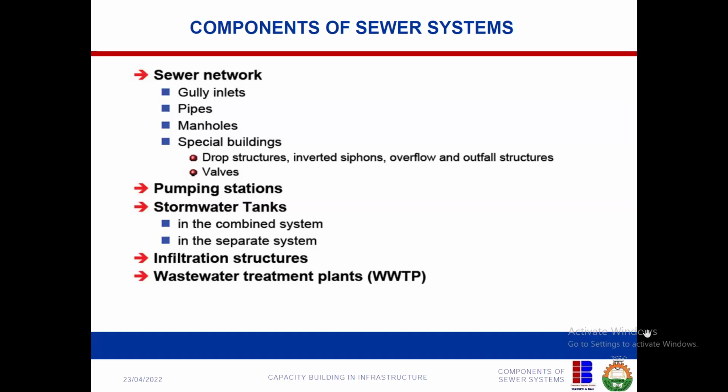However, when it gets to the treatment plant, in most cases you now need pumping to pump it back to the ground level. In the case of Abuja, for instance, the difference between the normal ground level and the intake of the treatment plant is about 12 meters. So the intake of the treatment plant is always located at the lowest point.